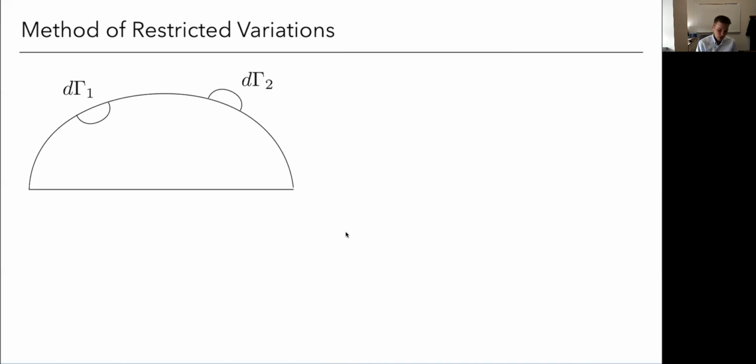Okay, so for minimum drag, though, I also want the change in induced drag to be 0, right? So remember from calculus that if I'm varying, let's say this is induced drag, to be at a minimum, that means that my slope here is 0, right? So I want also this change in induced drag to be 0. Well, we've seen from the Kutta-Joukowski theorem, what if this is V infinity, this is my downwash, this is lift, and this is now my induced drag, that the induced drag here I could get from rho W cross Γ, right? That's my induced drag from the Kutta-Joukowski.